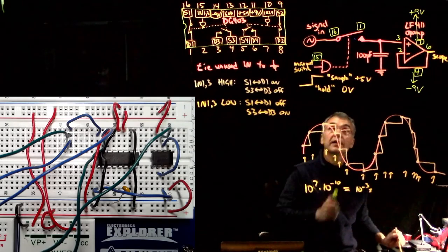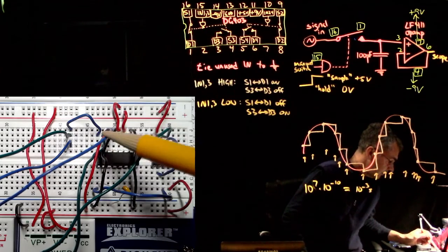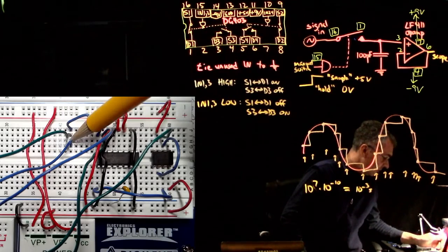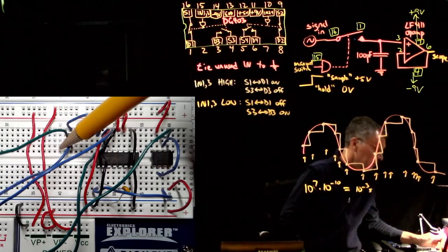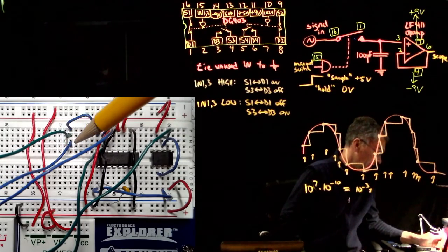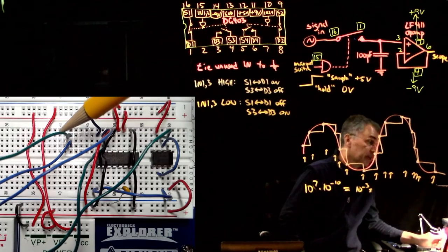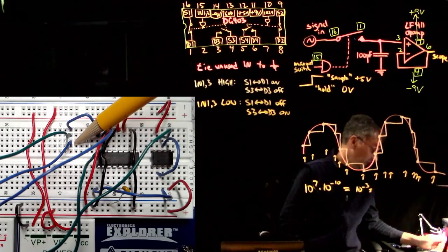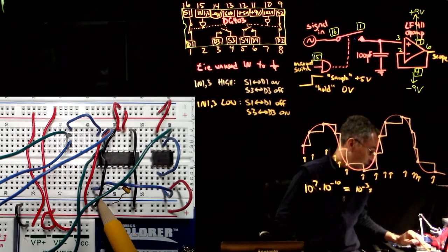So we have our signal going into pin 16. For whatever reason, I made those connections over here, left over from a previous circuit. So this blue wire is AWG channel 1, which we'll see in a moment is a sine wave. This green wire is scope channel 1, the yellow scope channel. So we're just watching what we're sending in. And then this little blue wire is jumping over to pin 16. Okay, so if the switch is closed, then pin 16 gets connected internally to pin 1.